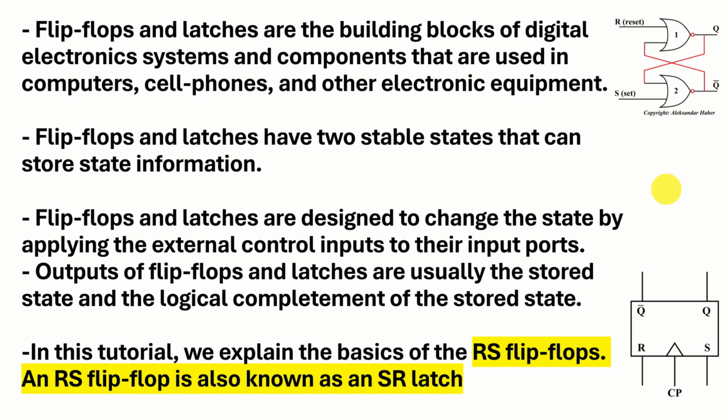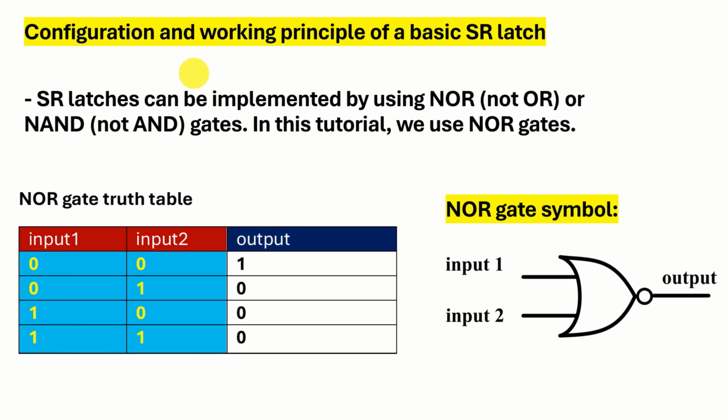In this tutorial, we explain the basics of the RS flip-flops. An RS flip-flop is also known as an SR latch. In the sequel, we explain the basic configuration and the working principle of an SR latch. SR latches can be implemented by using NOR, that is not OR, or NAND, that is not AND, gates. In this tutorial, we use NOR gates.